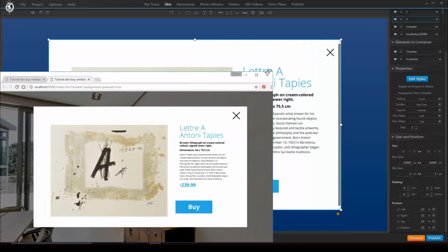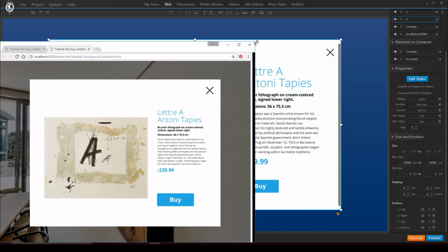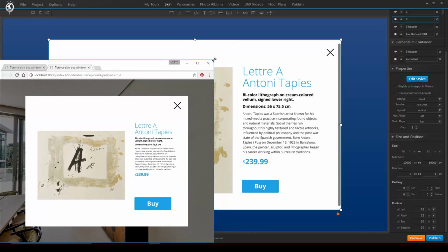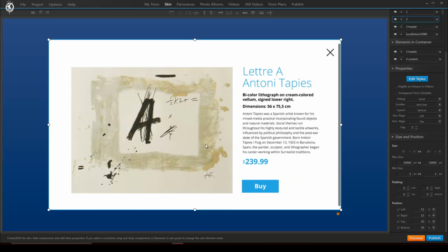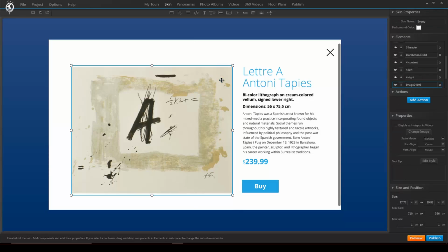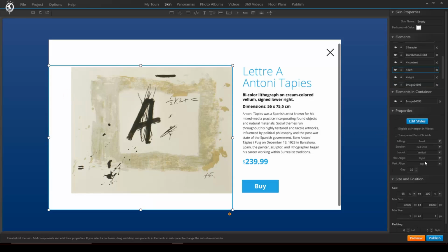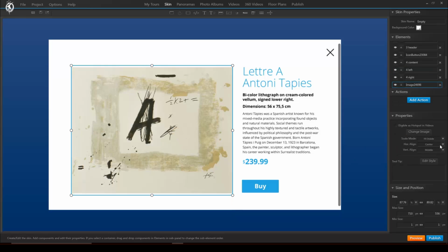Okay, the individual elements here adapt as we wanted them, but there's still a little glitch, because this right here should always be aligned, or at the same height, as the content of the text image to the right here. But these are errors which we'll fix right now. The reason that this is not completely aligned is that this image, even though we set the container to align its content on the top right, the image itself we also have to set to align on the top right.